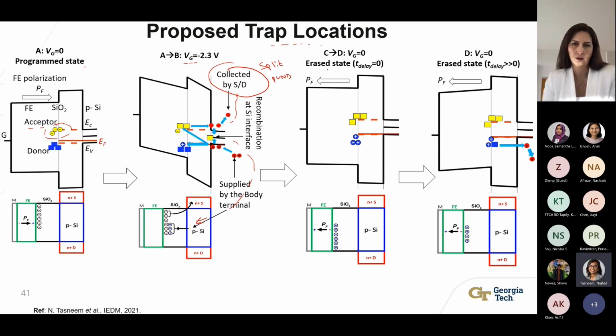Now, once the erase is completely done, we have trap states in the donor level, which are filled. If we wait long enough, which means if the read after write delay is long enough, then this trapped hole starts getting emitted, allowing us to read a larger memory window.